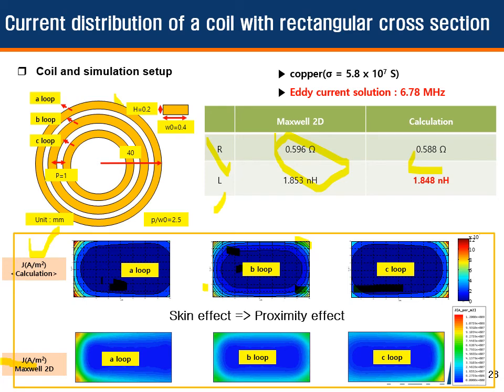I would like to say that the skin effect will make the current flow along the edges, and the proximity effect will make the current flow near 2 edges. Therefore, it is necessary to optimize a coil for better efficiency, that is, to find the optimal patterns with W0, total pattern width, large W, turn number, and metal thickness, with the coil diameter fixed and the metal thickness fixed.